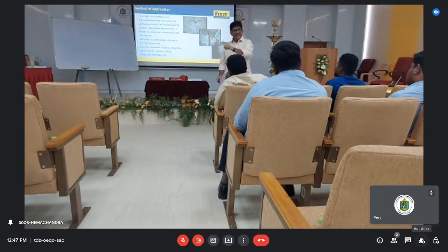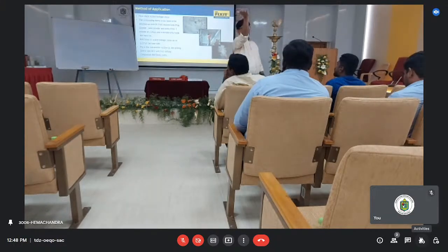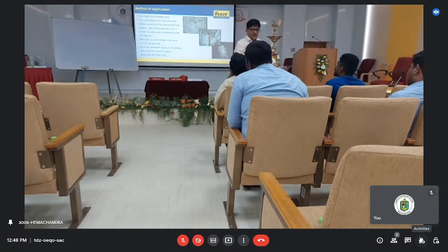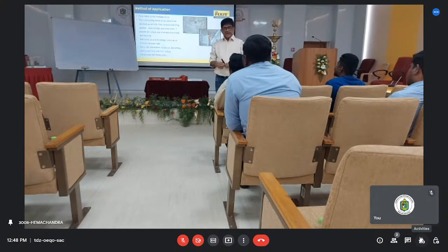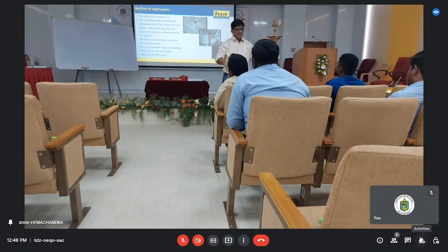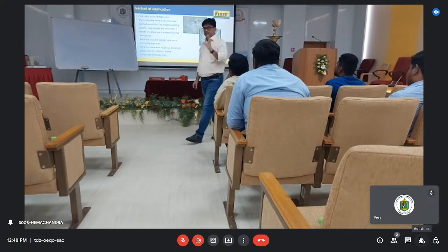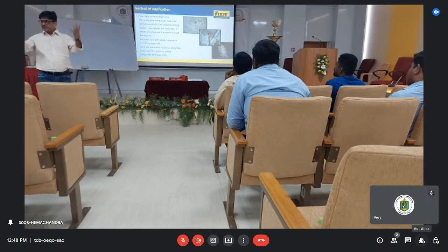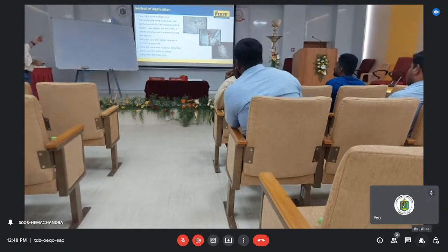Okay? So we get to the other steps. The water is coming, so just hold the material, it's a powder material. You hold the material for that, and it will immediately set. So it will not allow the flow of the water to come. Okay, so you are blocking the other areas so that the water is not continuously coming. Right? Okay, that is the second part of the process. But it is not a solution, it is only giving you temporary relief so that the water is not continuously coming. Then drill holes at the active leakages up to 2/3 of the base slab, as I told you. How to drill the holes?